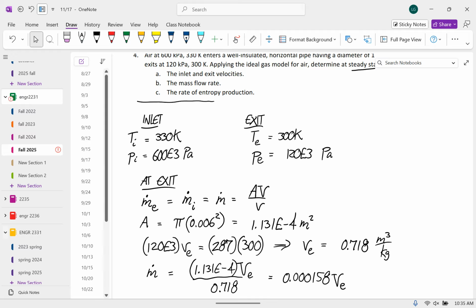And just one question for clarification. You can still use CP even if the pressure is changing in the example because it was always assumed that was meant. Yes, CP for an ideal gas only depends on temperature. And as long as that temperature range is reasonably small, you can get pretty good results.